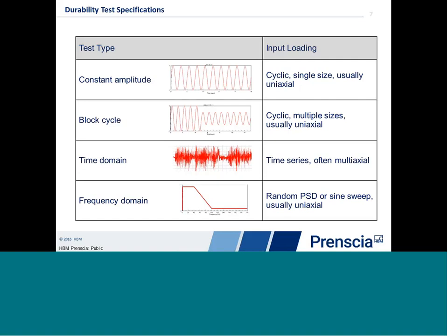in the lab. And we can use equivalent fatigue damage rules to figure things out like how big should this test cycle be? How hard should we push and pull? And also, how long should we do it for? So the critical metric in defining this test spectrum is how many cycles of what size.